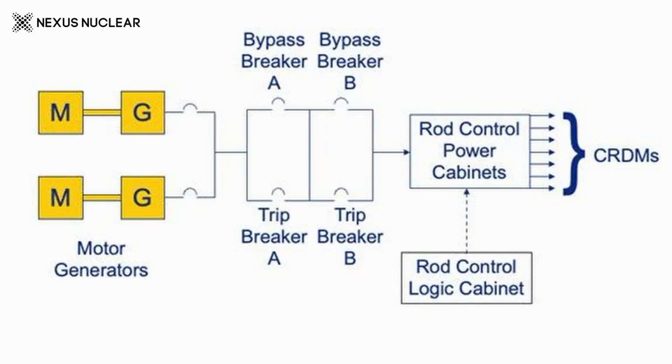For that purpose, we just trip the breakers, so the electrical supply to the coils will be deactivated. Immediately the control rods will be inserted. The action of the CRDM is to insert or withdraw the control rods, so that the control of the power, the reaction and the safety of the reactor happens.